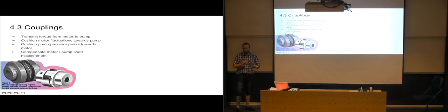And then in between these, you have some sort of elastic component, an elastic plastic, or maybe even a rubber component, so that they will rotate against each other, but they have this elastic part between them, which allows them to cushion each other. So you can get a jerk from the pump if it suddenly hits a pressure peak, and that's going to be cushioned towards the engine, so that the motor won't get the same jerk.